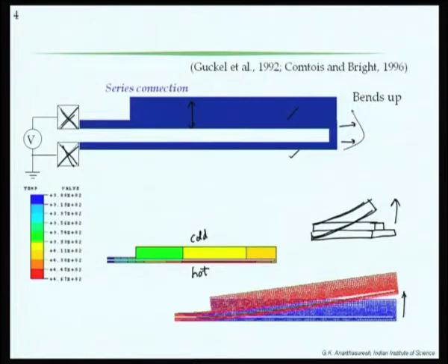So, we have to use the differential expansion not achieved with different materials, but with the same material, but introduce an appropriate bias in the design by getting the geometry right. Then you can create this mismatched thermal expansion and make it move. It is in plane, it goes in the plane of the wafer. So, like electrostatic actuation, you can generate in plane forces very easily. If you want it out of plane, we can just use bimorph and make it go, or the same structure can be put in vertically and the structure can be made to move up.